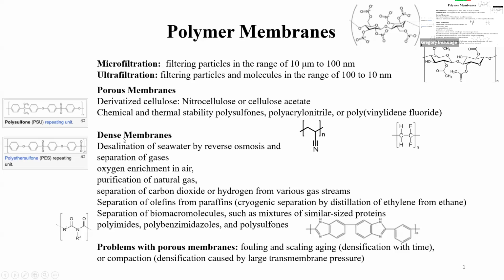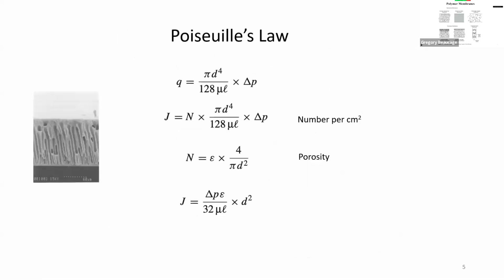So basically, the dense membranes aren't going to be just dense membranes. They're going to be something like this. So you're going to have a porous membrane, which could be a different material or the same material. There are ways to do this with the same or different material. There's going to be a solid film on the other end, right? So there's rapid transport through this part. Then all of a sudden you get to the slow transport through the film, and that's your separation layer.